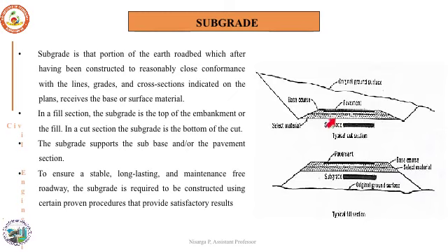The subgrade can be taken in the embankment portion if the original ground level is at a lower elevation compared to the required elevation of the pavement. So generally the pavements will be taken on the subgrade. If the ground is at a higher elevation compared to the required profile of the pavement, then cutting has to be done and the subgrade has to be taken at the cutting.